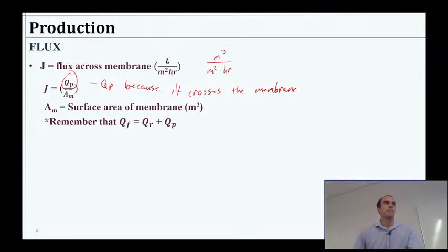Okay. We'll have a few other ways to calculate Q given some parameters, maybe pressure and some resistance that the membrane offers. But this one relates it specifically to the area and the flow rate. So this is a very convenient term when talking about the bigger picture design. So maybe we'll see, okay, well, how much area do we need if we have such and such a membrane and we can only offer it such and such a pressure, right? And then we can figure out how much membrane area we need to supply some demand.